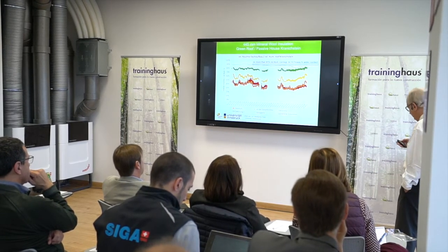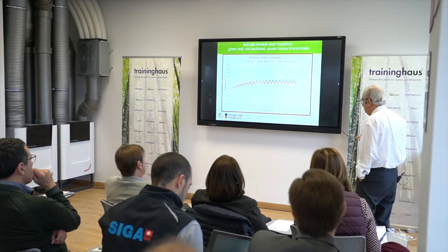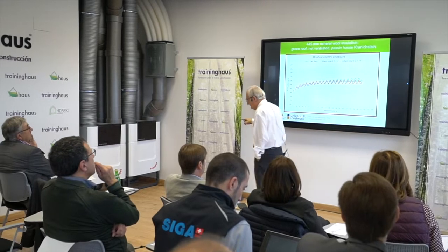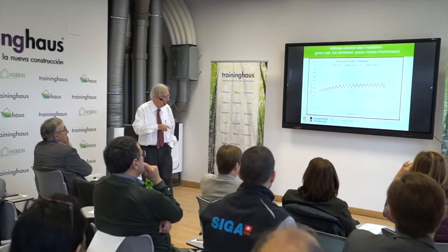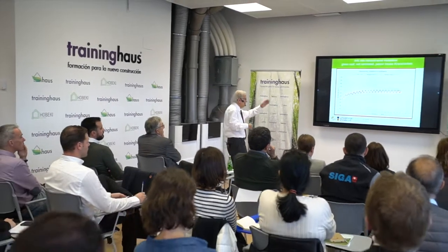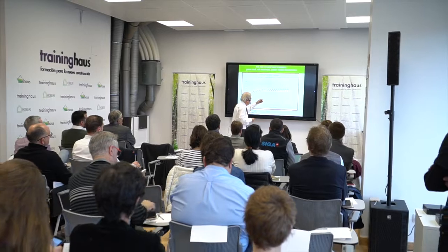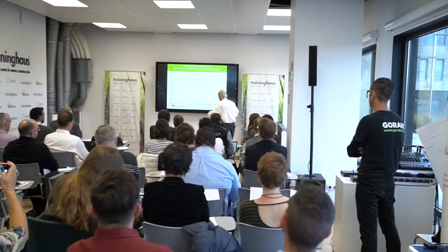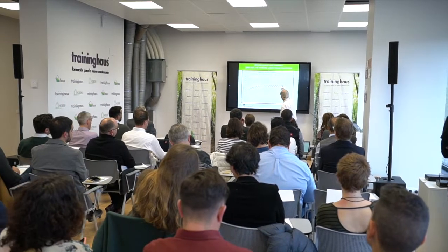Yeah, so that's demonstrating that this can work in the circumstances we already discussed: that it's really airtight from the inside, and the water vapor diffusion is somehow controlled. And we also did some simulations of how it would vary if we vary the material used for the inside vapor retarder. That is the vapor retarder we actually used, the blue one.